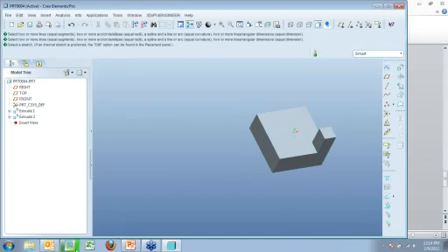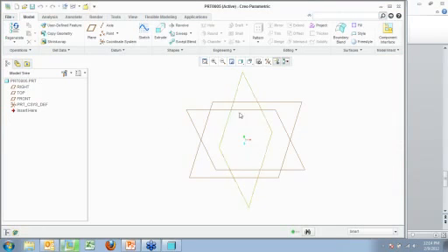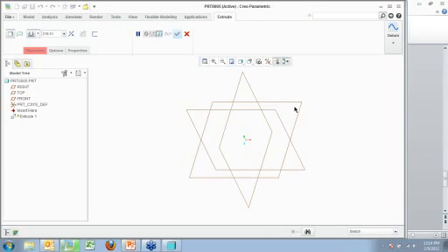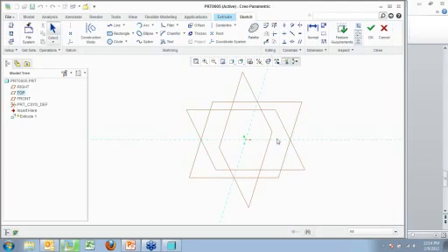Now let's flip over to Creo Parametric 1.0, and I'll show you how to do it the exact same way, or using a more advanced method; you'll see how much quicker it is. So extrude, click my plane. Notice it does not reorient to the sketch view. We'll talk about that again in just a moment. I'm going to go in. There's a new feature, center rectangle. Come in and make this so that that's there. Make this 250.